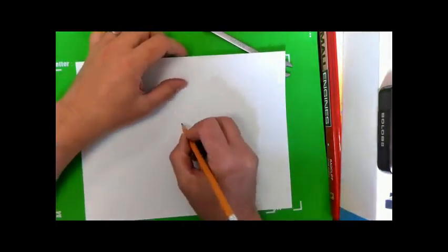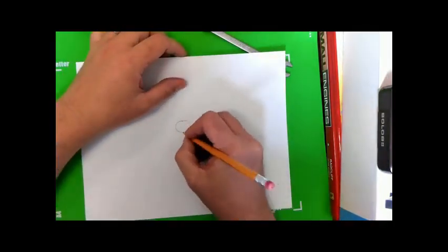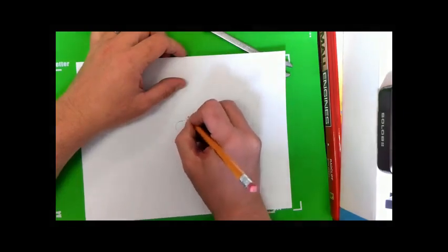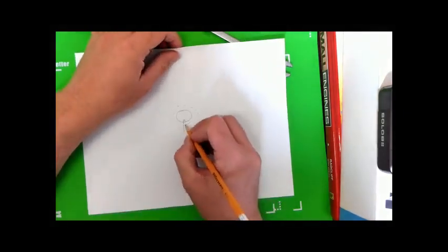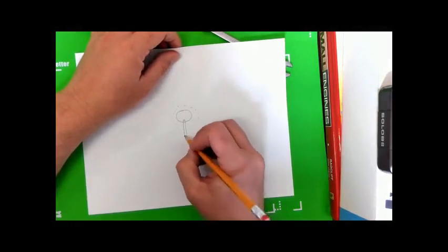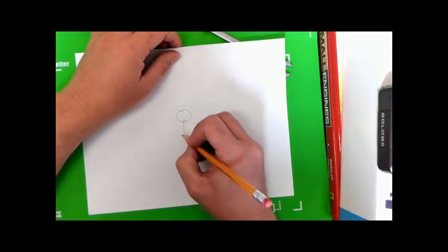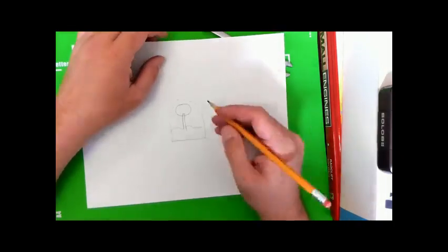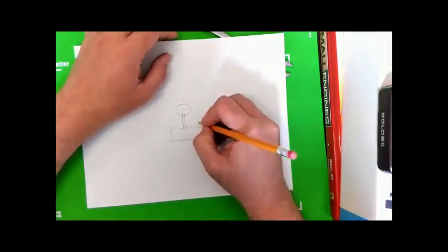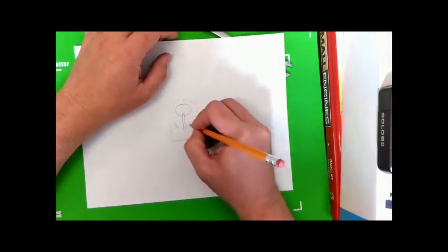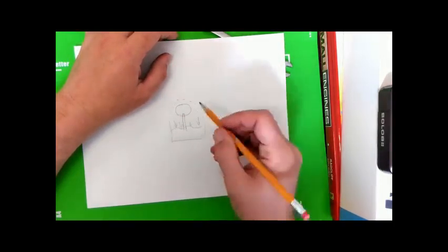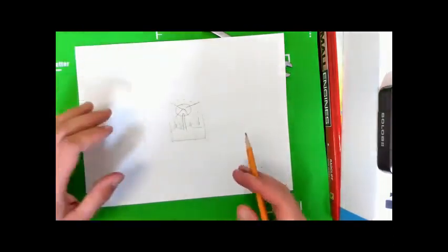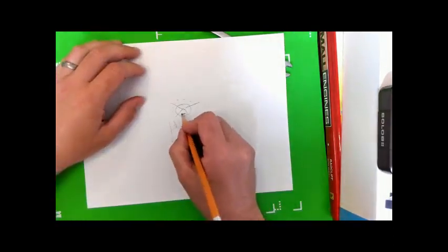So if I do a drawing of that venturi, and we know this is the big diameter of the carburetor. We've got that main jet sticking up. We've got a level of gasoline in our bowl. Atmospheric air is naturally just pushing down on this. We have air pressure pushing on us all the time, so does gasoline. And as this air goes very fast through here, it's going to actually hit this